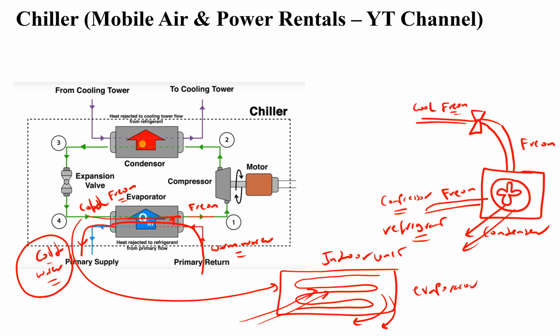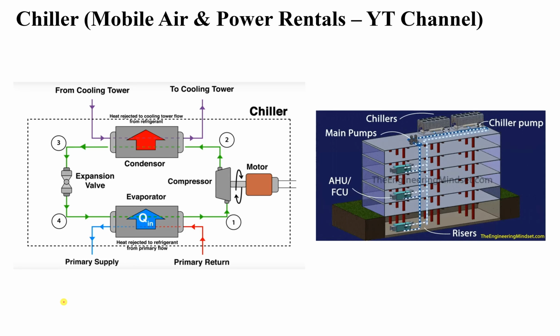the cycle repeats itself. So instead of exchanging at the evaporator, the heat takes from warm air and provides it with cold air inside like the DX system. The evaporator here is exchanging with hot warm water, and then we have cold water which will go through pipes inside our building. Now let's see this in animations like this.